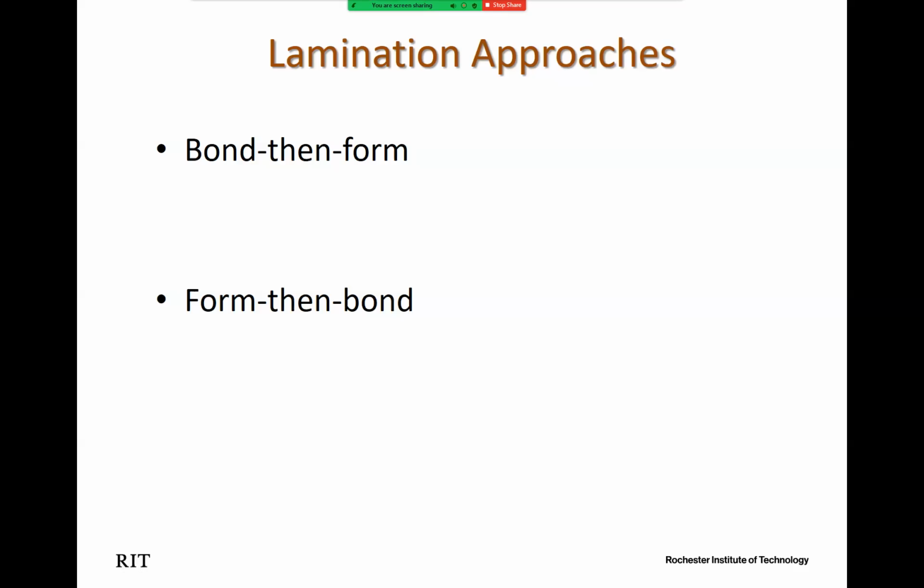That's quite different from what we have learned, right? In each of the other processes, you have to generate the whole layer, not just the contour. You have to have the infill created, I mean, the interior region of your layer. But in this case, there's no such requirement because you are talking about a piece of sheet for one layer. And that's the lamination process.